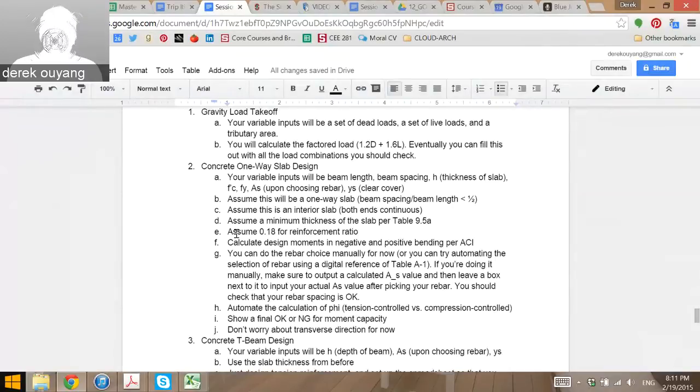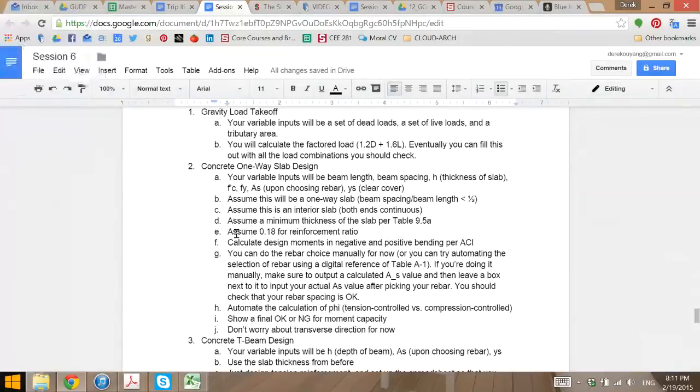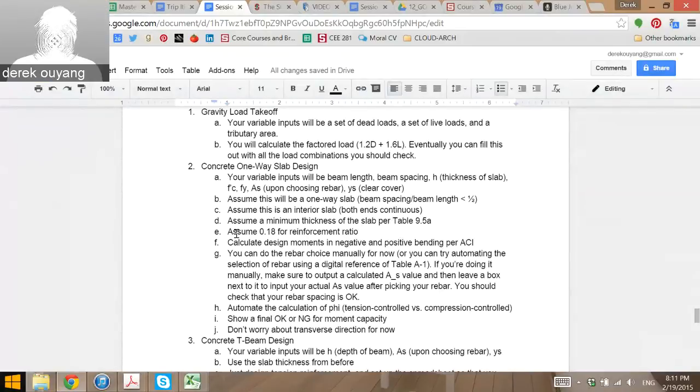Right? If you're talking about a condition here where you're putting uniform load on a beam or on a slab. So I don't care if you use WL squared over 8 or you're going to use WL squared over 12, I think, for your negative moment, max negative moment, stuff like that. And that's just what this value is. Well, I don't really care. And don't feel like you have to design for positive or negative bending here. Just assume positive for now. So you can put in WL squared over 8 here if you want. Same here.